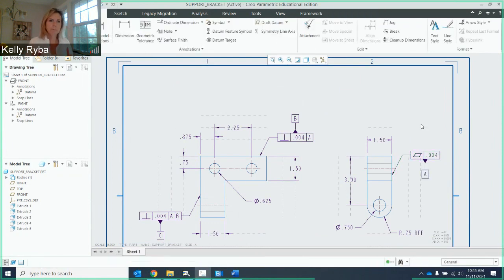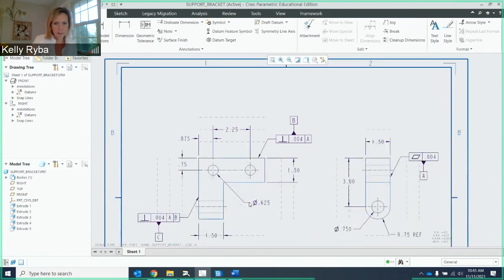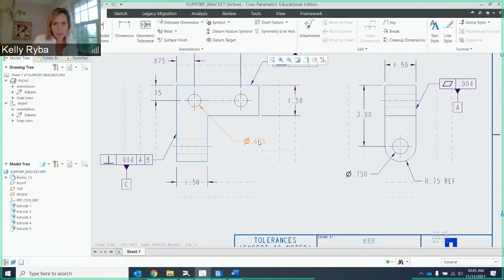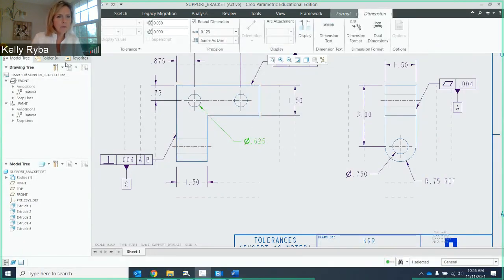All right. Okay, so I think we're all set up with our datums now. Now we need to add the tolerance to the 5/8 inch hole as well as the position for that. So let's go and look at this guy. So I'm going to click here, and first and foremost, we're going to set this to a limit dimension, and it's telling us that it wants the tolerances to be +3 -0. So I'm sorry, not a limit dimension. We want a plus minus, okay, plus minus. And notice that here is our dimension. I don't know why it's doing it to that. It should be 0.625.